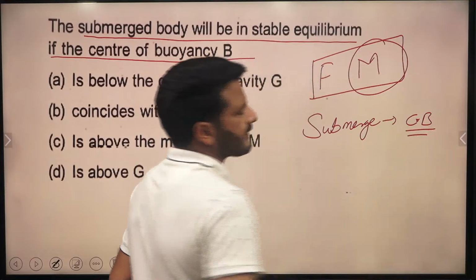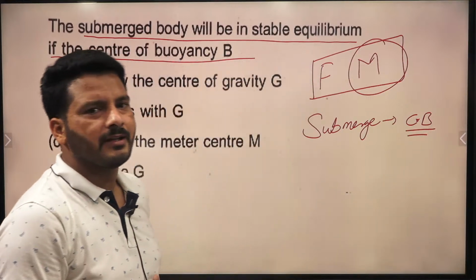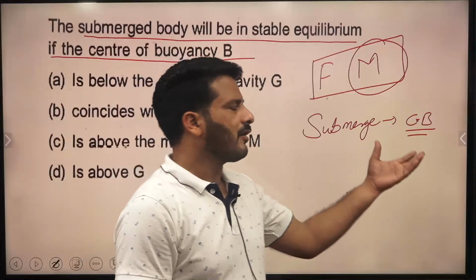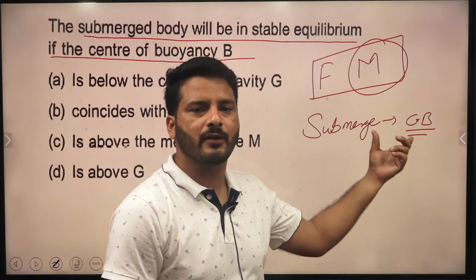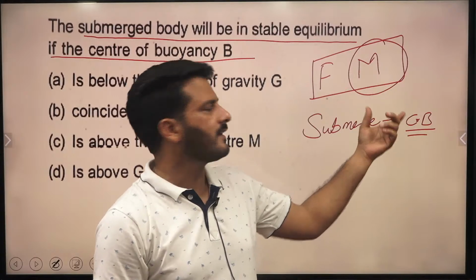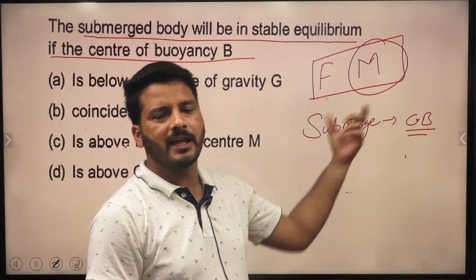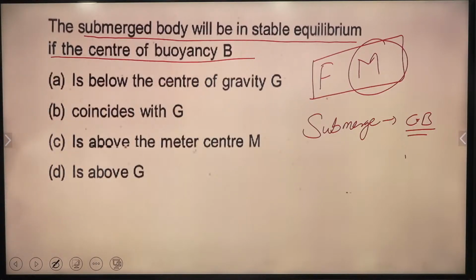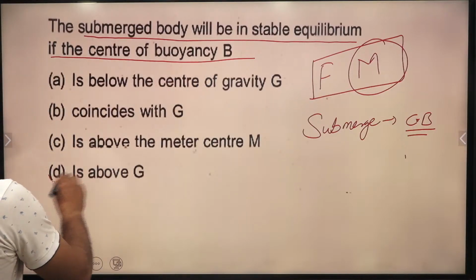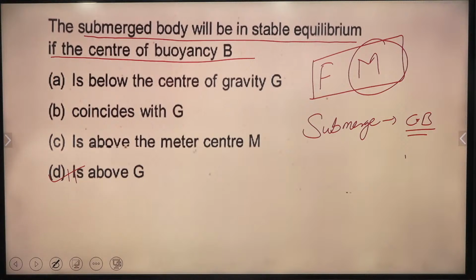Generally, metacenter above the center of gravity means stable equilibrium. The center of buoyancy above the center of gravity means stable equilibrium. Metacenter below the center of gravity means it is unstable. Basically the same thing here: center of buoyancy lying below the center of gravity is unstable. So he's asking about the stable equilibrium. Definitely the center of buoyancy is above the center of gravity. Fine.